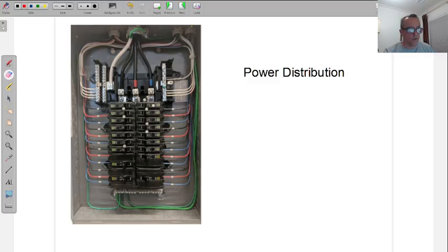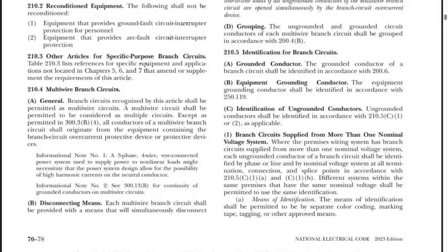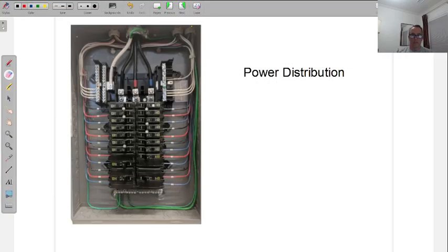I'll show you the code. This is why I went over to this one, because when you're an industrial electrician in a building, one of the things that you are almost 100%, if not 100% of the time, going to have is two different systems in the building, like what I was just showing you. You'll have the low voltage panels doing their job of feeding outlets and general low voltage electrical systems that need 120 and stuff like that. And then you'll have the bigger 480, 277 taking care of the lighting system, taking care of the larger equipment that needs the higher voltage to run.